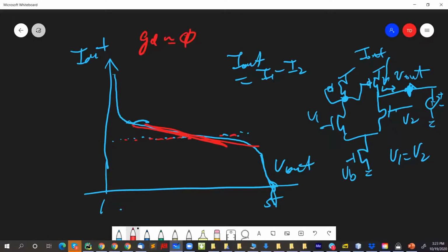Well, that happens because of the conditions that we saw about the current. The current that flows through each of these nodes, let me pick a color, do red, the current that flows through here and here depends on where this voltage sits. So you do affect the current flowing through these transistors. Because of that, the output current also changes. In other words, it's not I1 minus I2, but rather I1 plus delta I1, which depends on where V out sits, minus I2 plus delta I2. That's why you get this changing output current as a function of the output voltage.